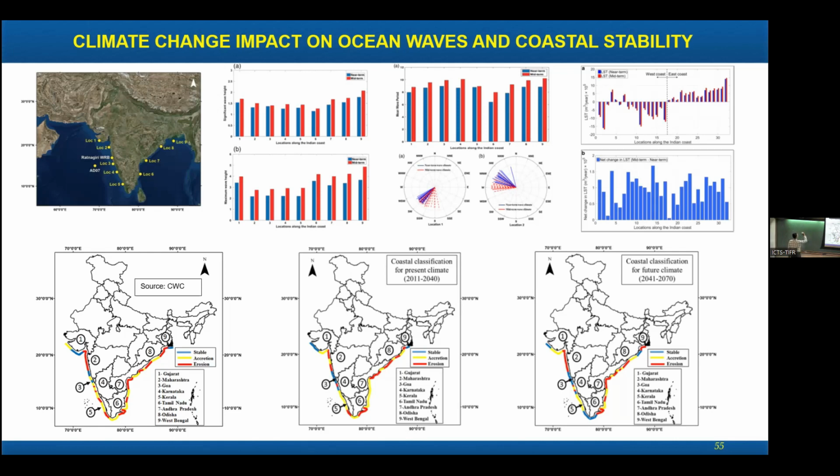I don't know whether I'm writing it correctly or not. Basically I'm taking the highest 1/3 wave heights and then I take the average of that. The value that I will get is called significant wave height. All the mathematicians, you can correct me if I have written it wrong. All right. So this is how we find a design parameter to be used.